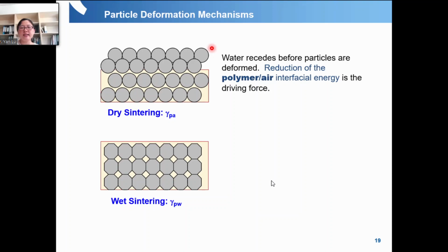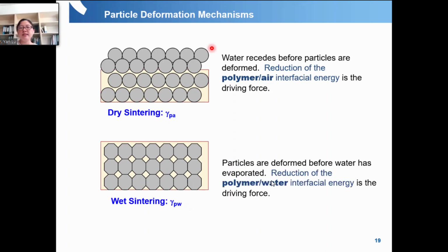And in the case where the particles are still wet, the water hasn't evaporated yet, the reduction of the polymer-water interfacial energy will be the driving force for the particle deformation. So these are two different cases. You should know this.